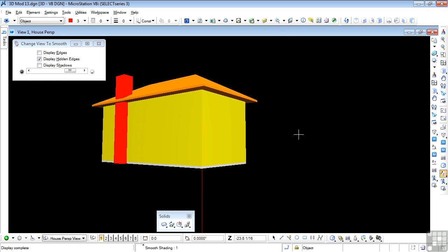Imagine yourself standing at that camera location, looking at this house, and your eyes are basically fixed at the midpoint of the front edge here. This is what you would typically see. Now this is a 3-point perspective, and you can tell that by the jagged lines here. If you look closely, you'll see that those vertical corners are actually sloping inwards. This is absolutely correct for 3-point perspective. Your eyes see this, but they typically filter it out in a real-life situation.